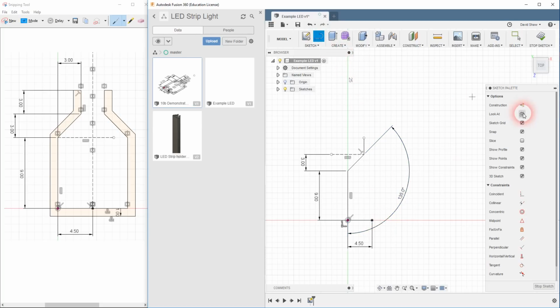L tool is another shortcut for line. Construction line, it's snapping to that point at the end of the line there. I'll go straight up there and I'll just secure that in place. Okay, so that's my line of symmetry around the center of the drawing, which you can also see identified on the sketch here as well. Okay, so let's now just escape that line tool.